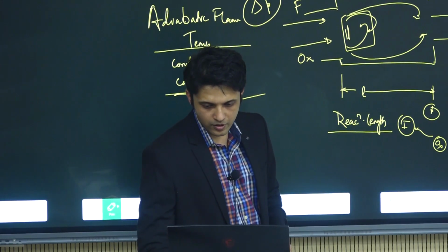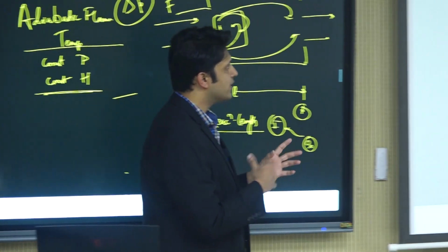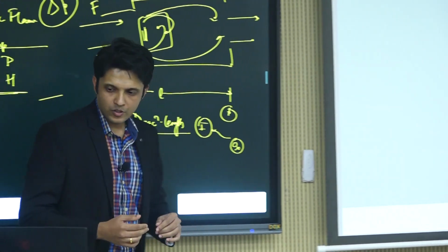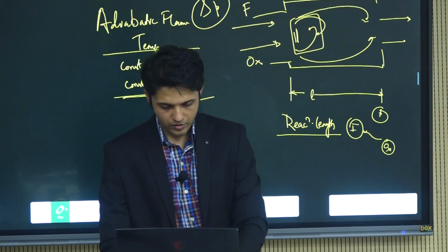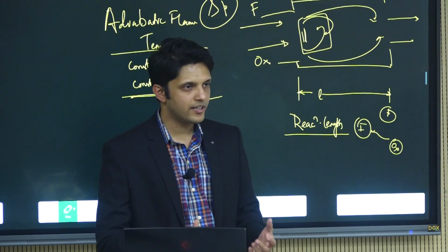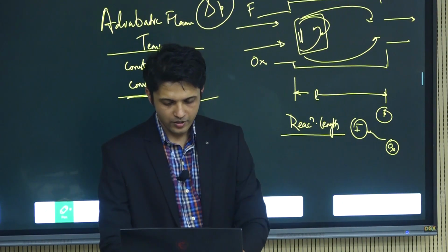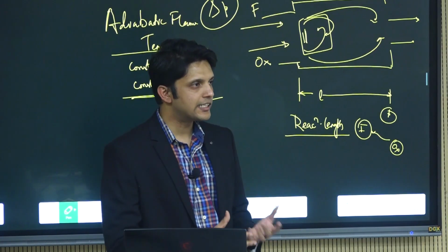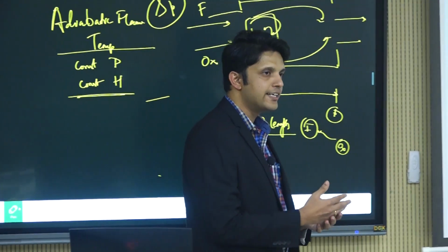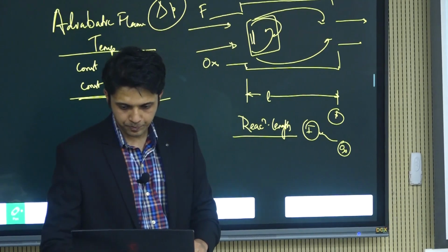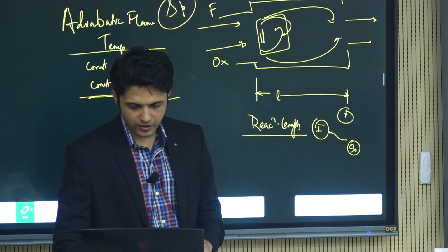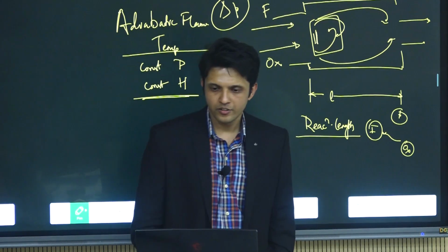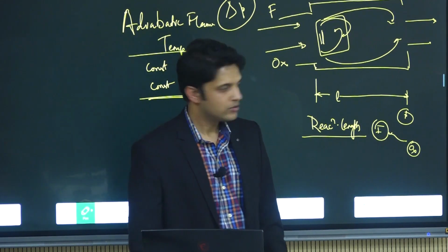After this, we add any additional species that were not in the reactants but could be there as products. Those are CO2, which is something additional that is a product, and H2O, water vapor, that can form. For now let's consider these. There could be additional products, but we're not considering dissociation reactions and things like that. Once we do that, we ask it to calculate. It probably takes a few seconds. Okay, done.